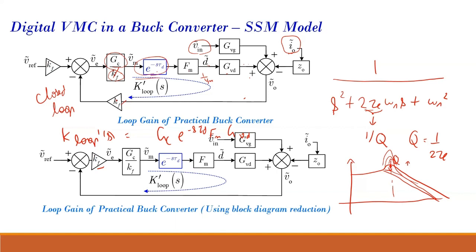Can we write it? If yes, how can we do so? Yeah, for that you'll have to write the expressions, derive the transfer function, and then you can write the quality factor expression. But in a normal case, we ignore those resistances because they are quite negligible, unless you want a really accurate one.